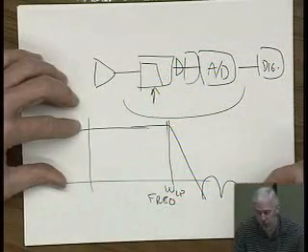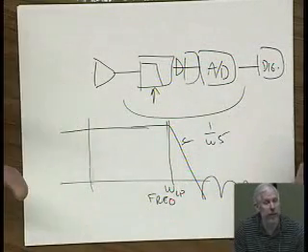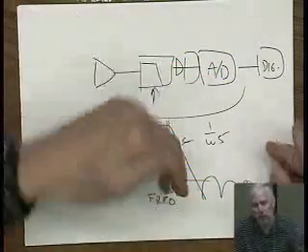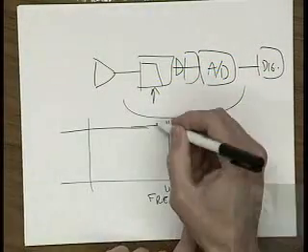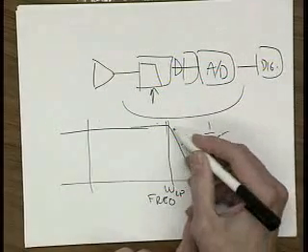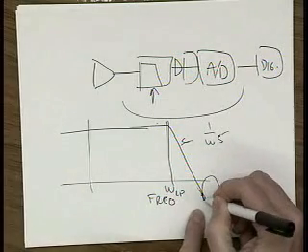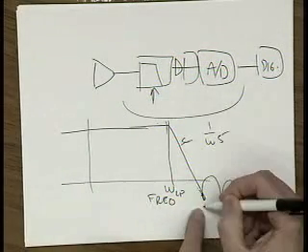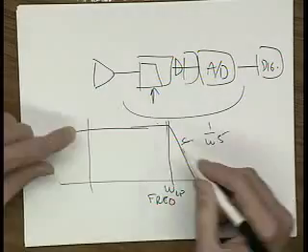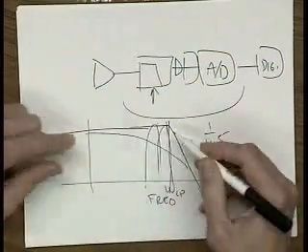We'd like to have this thing fall off maybe like 1/f^5 or something like that. I mean, lots of poles. And we use zeros as well as poles to make this thing fall off. If we put a zero near that edge, the response goes to zero there, and we can place it as close as we can. It'll drop this response as fast as we can. We don't want this to tail off like this, so we put some poles in quite often to keep this up.